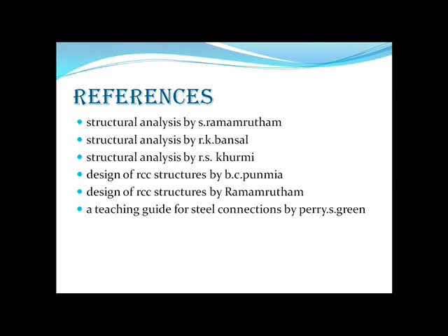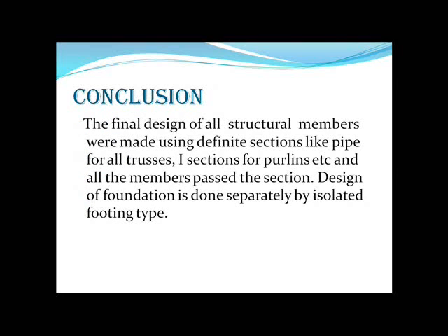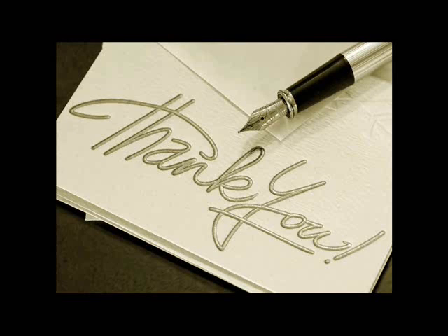Design of steel. The conclusion is that the design of all structural members was made using definite sections like pipe for all trusses, I sections for purlins, etc., and all the members passed the section. Design of foundation is done separately by isolated footing type.